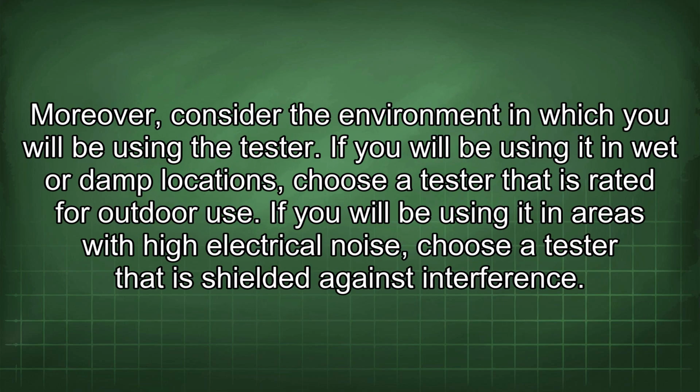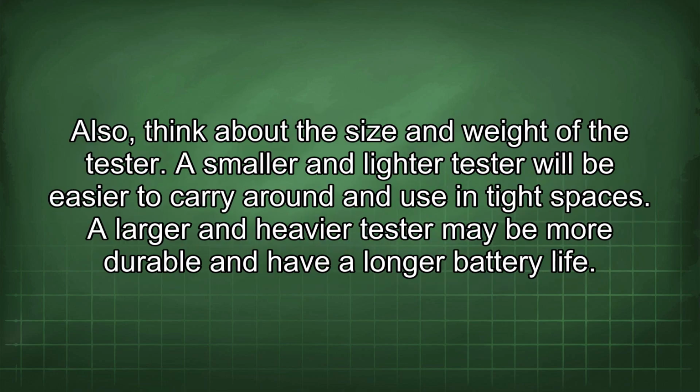Moreover, consider the environment in which you will be using the tester. If you will be using it in wet or damp locations, choose a tester that is rated for outdoor use. If you will be using it in areas with high electrical noise, choose a tester that is shielded against interference. Also, think about the size and weight of the tester. A smaller and lighter tester will be easier to carry around and use in tight spaces. A larger and heavier tester may be more durable and have a longer battery life.